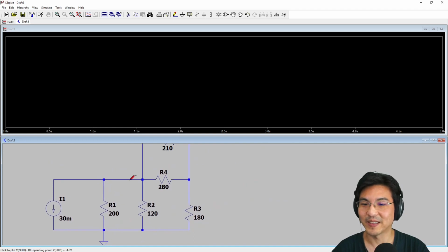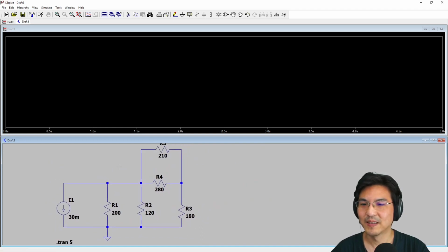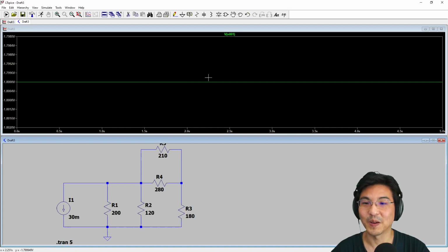But now, how do we analyze what's going on in our circuit? So if you just drag your cursor around, you see how this icon pops up of a probe? So this is a voltage probe. Right? If I put it on the nodes, there's this voltage probe icon. But if I drag it across over a component, see the icon changes? Now this is measuring current. So see the icon? Voltage, current. Voltage, current.